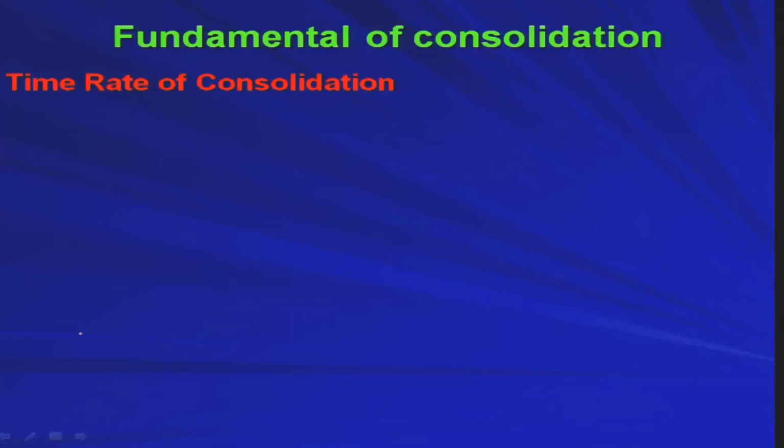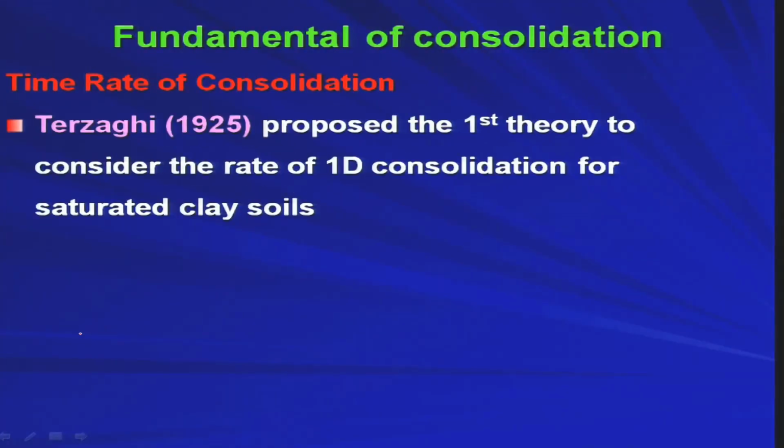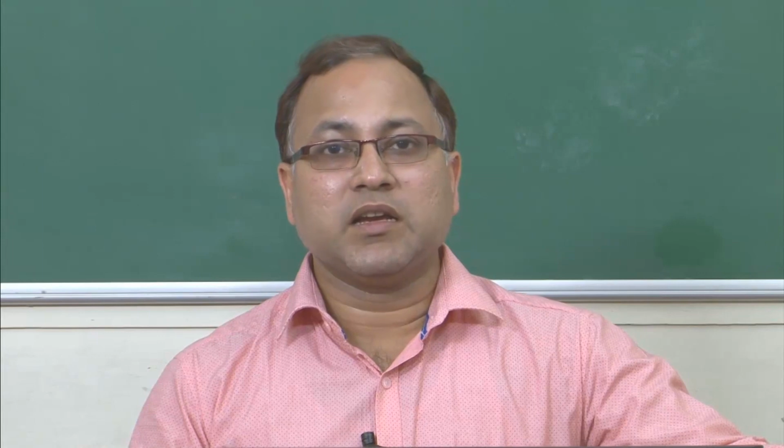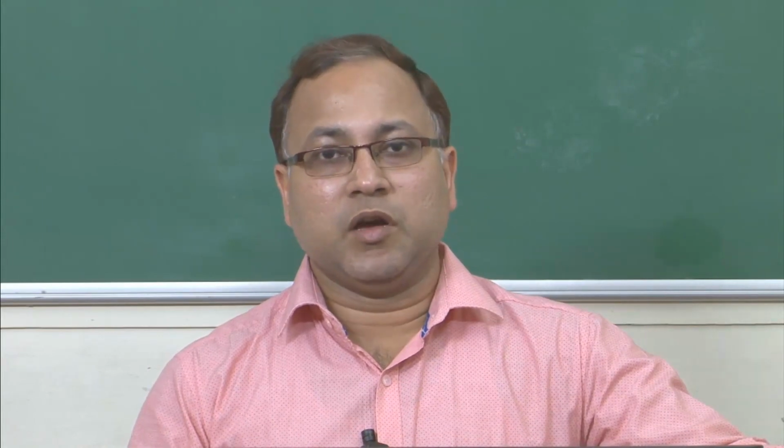Now, time rate of consolidation. Terzaghi in 1925 proposed the first theory to consider the rate of 1D consolidation for saturated clay soils. Now, we will try to develop the 1D consolidation theory. Based on that, we can calculate the consolidation for a particular deposit under completely saturated situation.